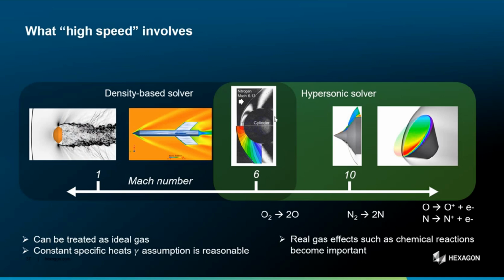First one, you refine everywhere because you don't know where the shock wave will occur. But of course, it's a very heavy model, very long calculation. Second solution, you use our tool, because in our tool, we are able to refine dynamically. So it's what we call the automatic mesh refinement. Locally, along the cycles that you're solving, it will refine where the gradients occur. It saves massive amount of calculation time.